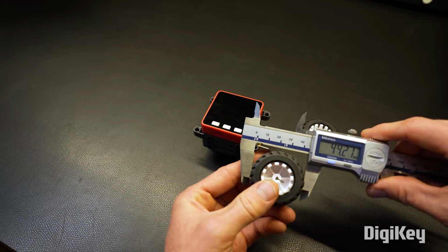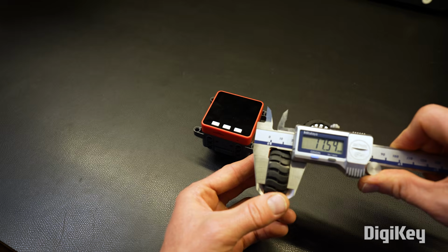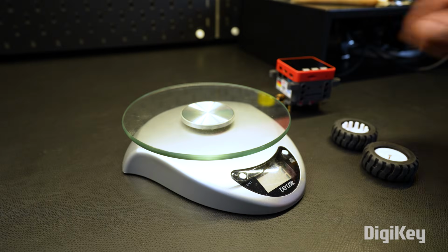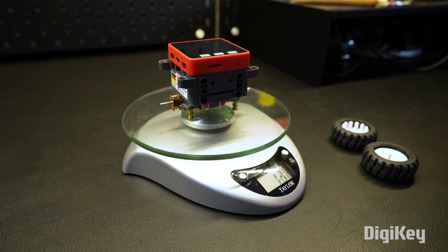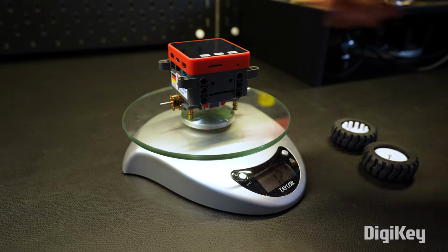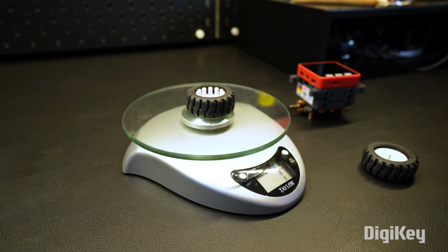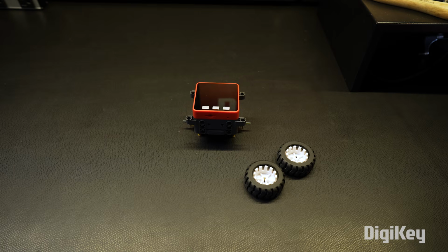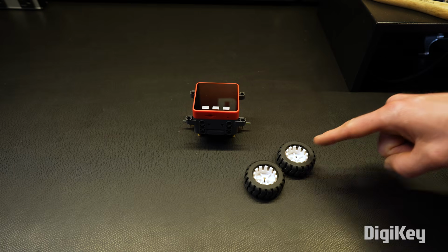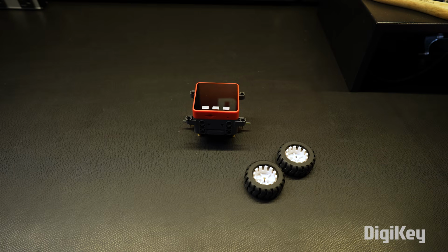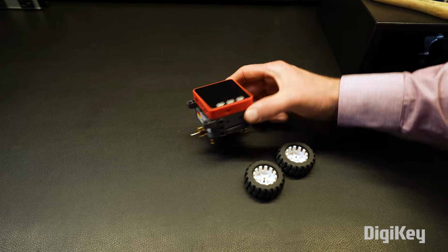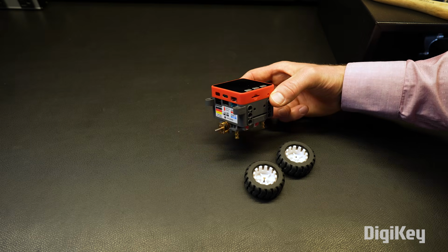I'll do my best to measure where the axles are in relation to the chassis. We also need to know the mass of the 3 parts, so I'll weigh the chassis and wheels on a kitchen scale. I'll record the masses of each in grams. We need to know where the center of mass is for all the parts, as MuJoCo uses this information to simulate the physics for those parts. This information is also crucial for tuning a balance bot.